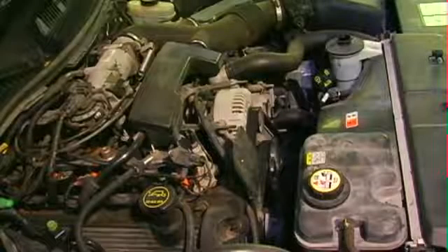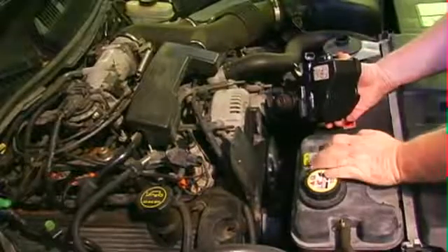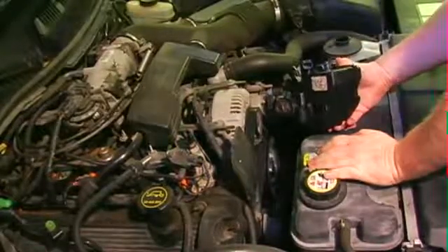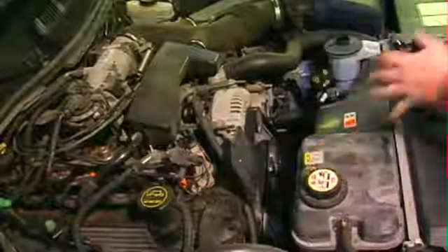Well, hydraulic power steering has been around for years, and there'll be basic questions on the A4, but there's also going to be questions about something more in detail of high-tech power steering systems, and that would be the variable effort power steering systems. Here we have a General Motors EVO, electronic variable orifice, and as we get a close-up of the solenoid right here, this solenoid is going to be turned off and on as a duty cycle, pulse width modulated duty cycle, and that's going to control the pressure output from the pump.